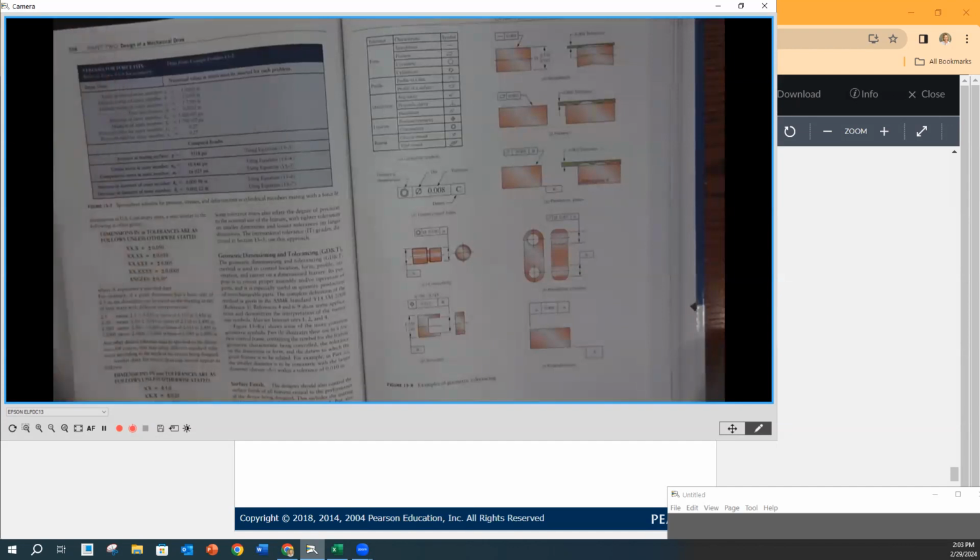can you imagine making a drawing for that, where profile could be like, all right, on this basic, theoretical profile, now I'm going to attach a tolerance, whether it's the same on either side or if it's different, we can control that. But it's evolved into, you can apply it to flat surfaces or rectangular types of parts or circular parts too. It really is very versatile. So you've got your profile there.